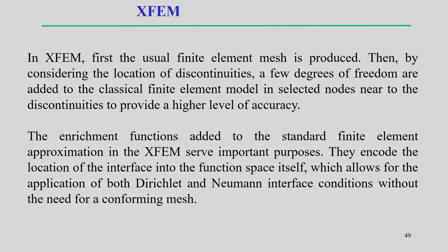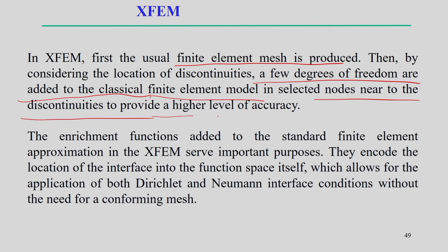So, we can see that in XFEM, first the usual finite element mesh is produced. Then, by considering the location of the discontinuity, a few degrees of freedom are added to the classical finite element model in selected nodes only, near the crack or discontinuity, to provide a higher level of accuracy. So, few degrees of freedom are basically added in the selected nodes near the discontinuity or the crack. That way we can develop the extended finite element method.